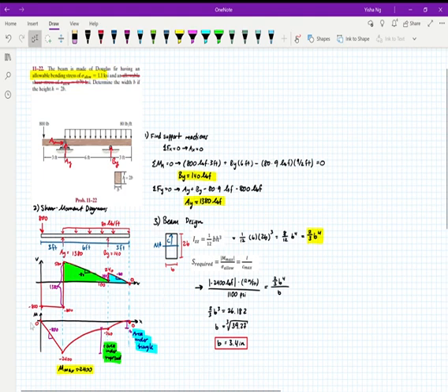From the shear diagram, I'm going to draw my moment diagram. So we start at 0. Because our shear value is negative 800, my moment is going to be at a slope of negative 800. From 0 over the course of 3 feet, we get to negative 2400, which is 800 times 3. From here, I have a triangle, so I know that this is going to be a quadratic. It's above the x-axis, so it's positive, so I'm going to be increasing.